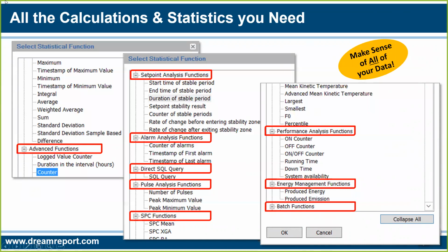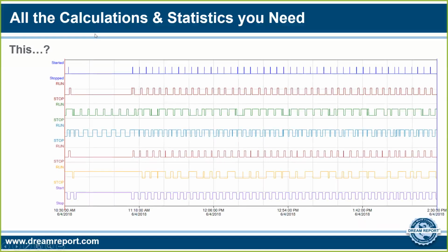Then simply put on the screen timestamp minus 1 hour or timestamp plus 15 minutes, and then put another table, for instance, status of all my pumps, with the time period not being the last 15 minutes, but what we call a calculator that points to the two, time minus 1 hour, time plus 15 minutes. So very quickly, you've taken from when did that maximum flow occur, and then show me a bunch of other information that helps me understand why that max flow occurred leading up to and just after, or maybe show me the alarms during that period, or whatever it is you want to do. And another example.